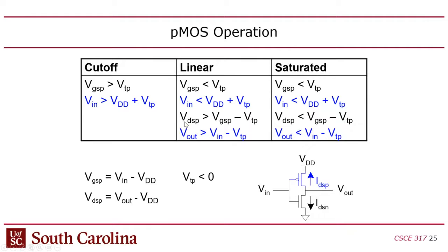And then the difference between these two is if the gate voltage minus the threshold is less than the total voltage drop, drain source. Again, these are all negative values. So you'll notice that in linear mode, the gate voltage minus the threshold is less than the total drop across, and it's greater in saturation. Greater meaning that you're pinching off, right?